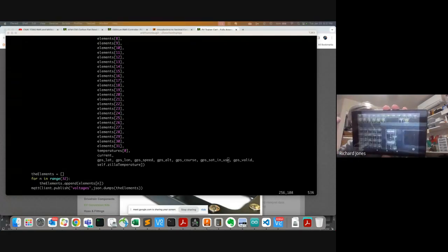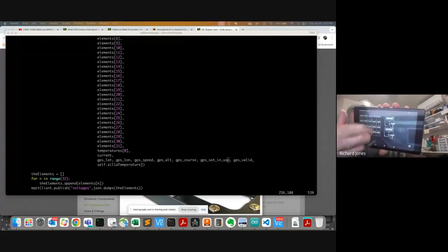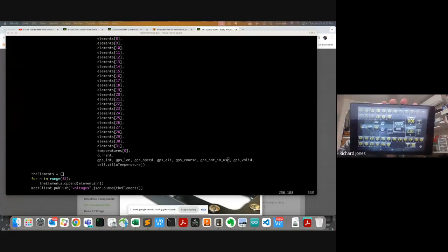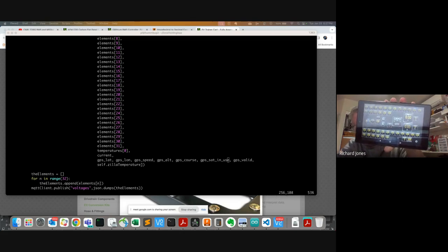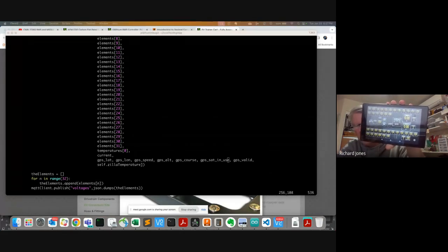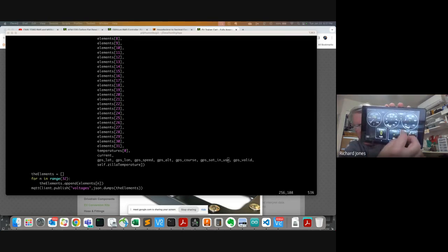And in Torque, you can make your own displays. This came out of one of the vehicles I did, and this is showing cell voltages down here and currents and things like this, data you might want to look at from your vehicle. So similar to what Kevin was showing on his Raspberry Pi and the display, this is showing instantaneous data on different screens, depending whether you're driving or charging or whatever.